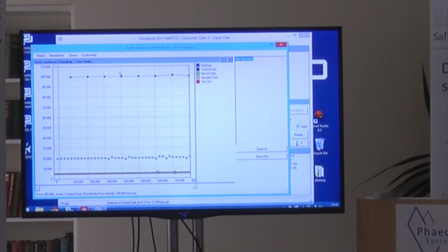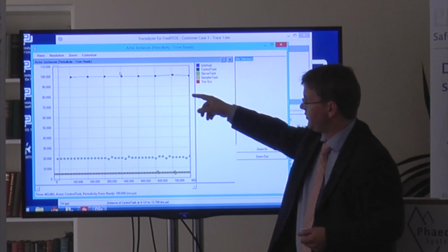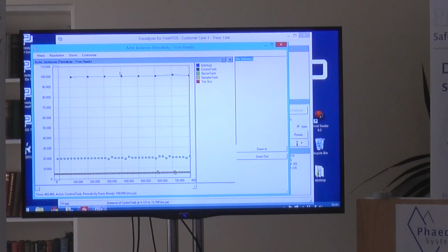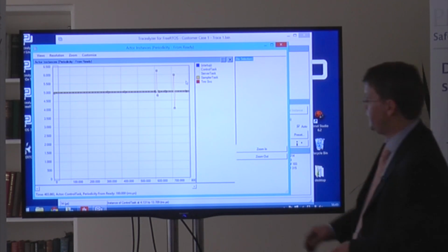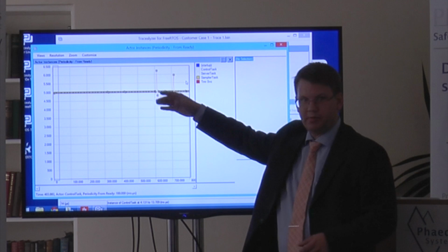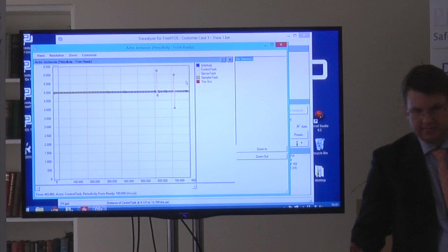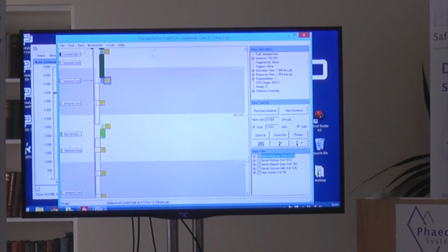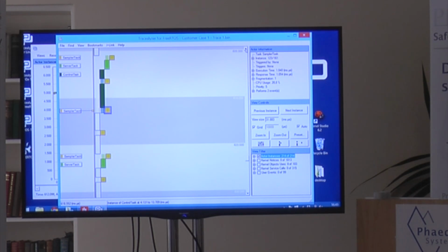Here we can see the time between activations of a task. Here we have 3 different application tasks. And if we filter this a bit, we can see this particular one in more detail. And here we see that we have a quite steady behavior, 5 millisecond inter-arrival time of this task. But here we have 6.5 milliseconds all of a sudden. Why is that? Now if we click on this data point, we focus the view here, and when we have anomalies like this, one could suspect that it has to do with the operating system scheduling.